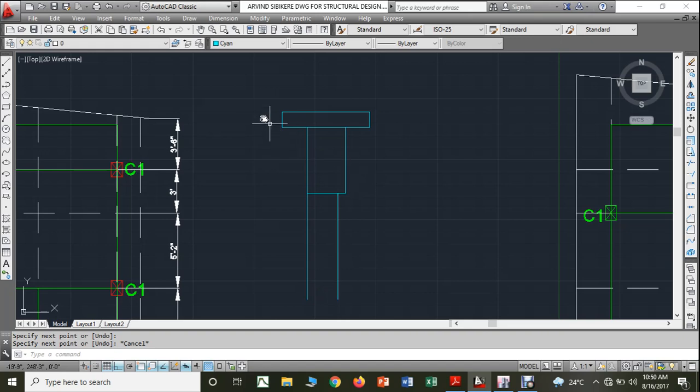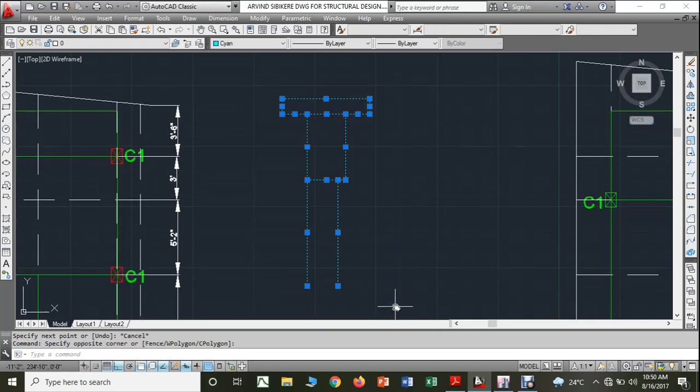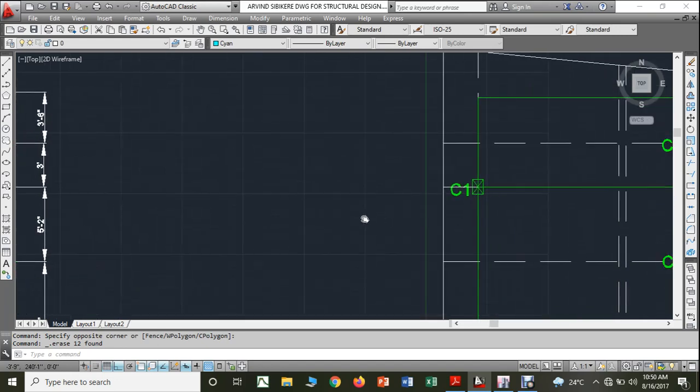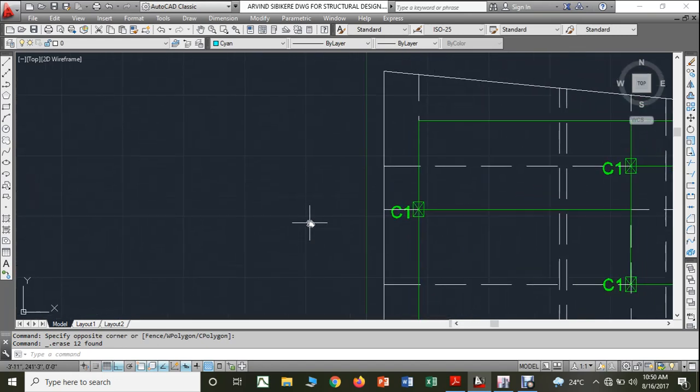Therefore, in our problem, the width of the beam will be restricted to 9 inches because we are using 9-inch walls. Only the partition walls are 5 inches. Other than that, all are 9 inches. So we restrict the width of the beam always equal to the 9-inch walls. Therefore it will be 9 inch. Only the depth of the beam is going to vary.